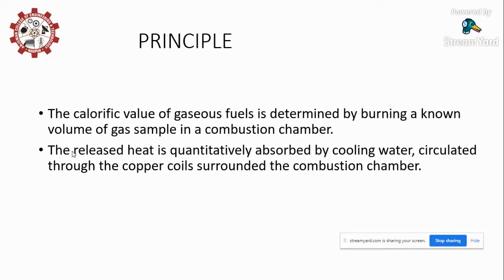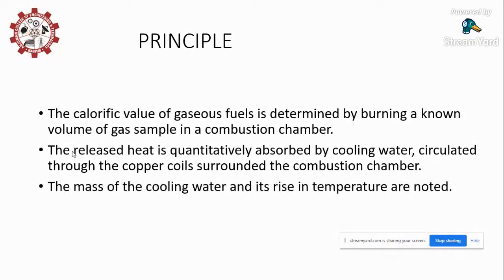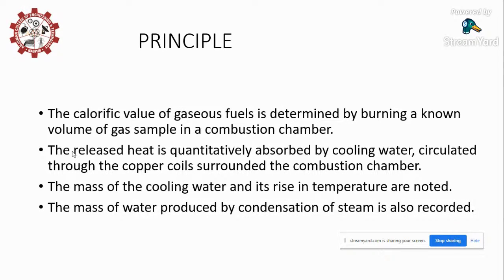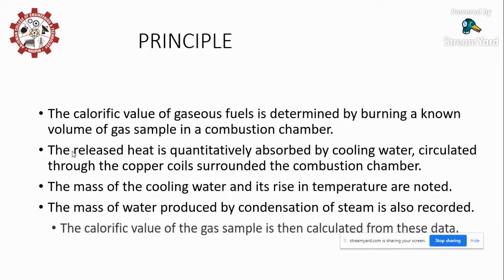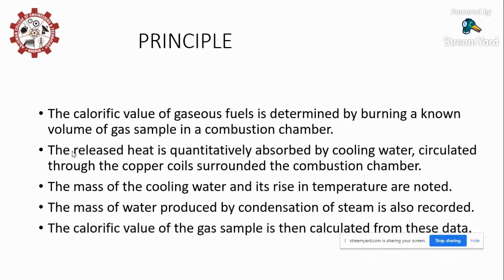The mass of the cooling water and its rise in temperature are noted, and the mass of the water produced after the condensation of steam is also recorded. The calorific value of the gas sample is then calculated from the data collected.